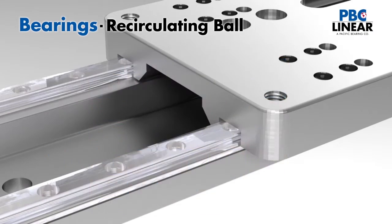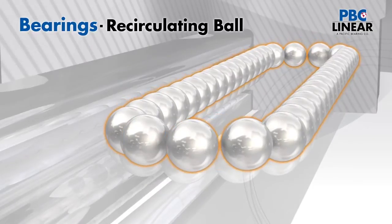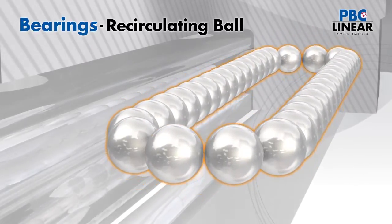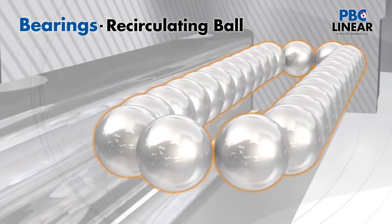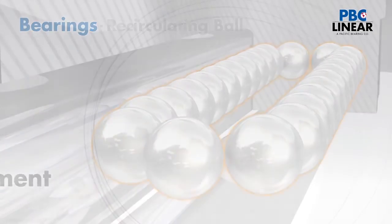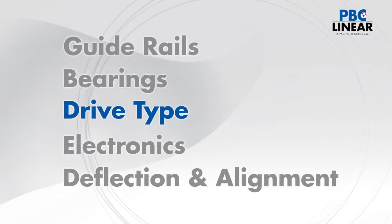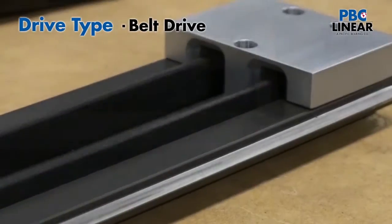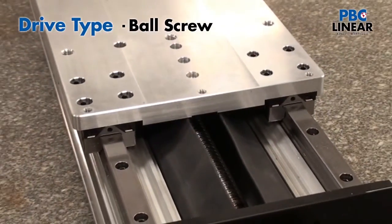The trick is that slightly larger balls are inserted into the bearing raceway to increase the amount of engagement with the shaft or rail. Rigidity is achieved, but the life of the components will be shortened and premature failures may occur. One of the biggest areas of concern when evaluating positional repeatability and accuracy is the type of mechanical drive system utilized.